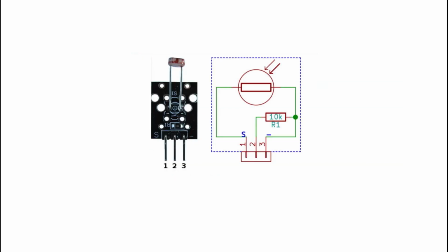As I went on to test this further, I did encounter some issues early on with my light-dependent resistor. When I was first working with my LDR and my prototype setup, I was slightly puzzled as to when my sensor was telling my system it was either bright or dark. Upon further inspection and some research, I recognized that this particular LDR is configured such that in bright light, the LDR's resistance is low, so the voltage at the node, and hence at my analog pin, is closer to ground.